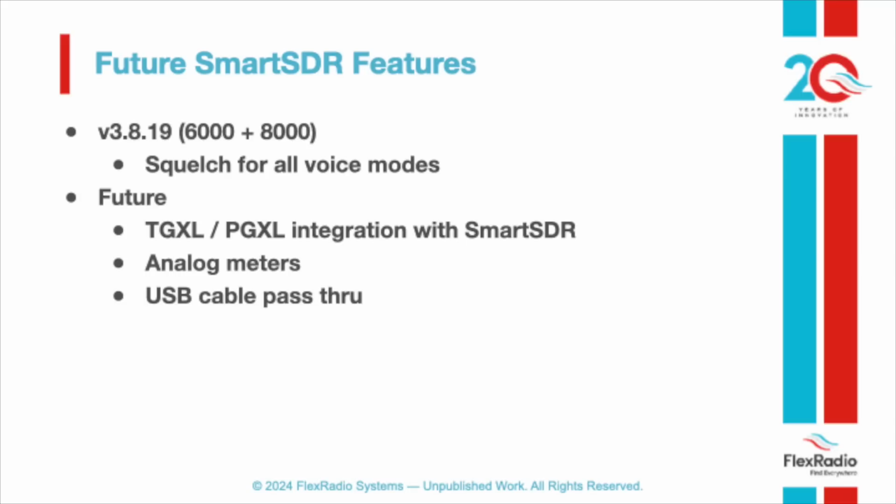The brief idea of that is, let's say you have a rotator that you want to control remotely. You can plug the rotator in through an RS-232 USB cable in the back of the radio, and then on the remote end where you have a computer, you can plug a cable in there or use your rotor control software on the computer, and it will tunnel through the Ethernet connection to the radio and pop out on the serial connection. So if you had a rotator control application that's expecting a COM port, you can run that on your remote PC. It tunnels through the Ethernet and controls your rotator remotely, or whatever else you happen to have that you want to control.